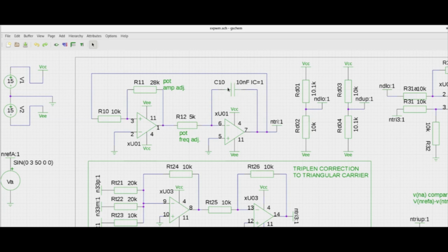Because of the capacitor, this will discharge, and this voltage is going down, and as it is going down, once it crosses the hysteresis lower trip point limit, this will go low, and again this will start rising because there is a change in the state here. Now the current flows and charges up this capacitance, and this will rise, and then again if it goes above the upper trip point, this will change state, and so on.